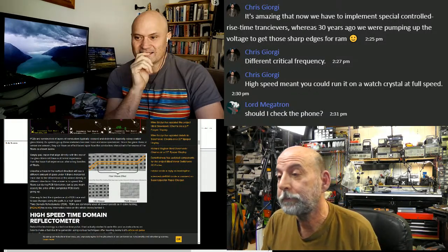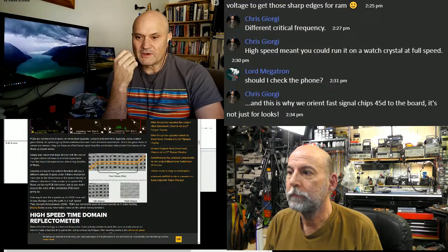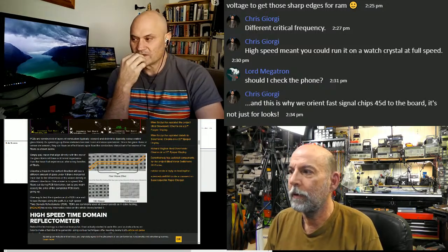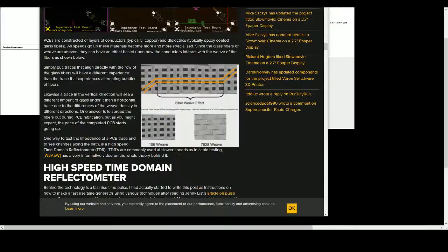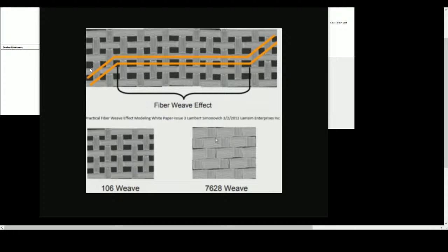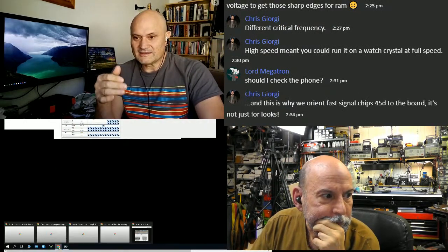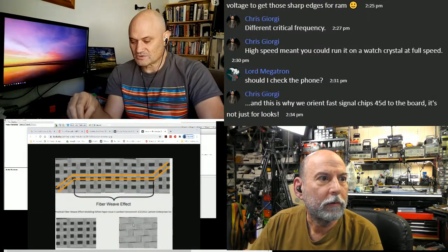Yeah. The theory, though, is common mode noise. Common mode noise is easy to reject because the receiver is only looking at the difference between them. That's why they're called differential pairs. But the problem on PCBs and chips is it's kind of a moot point because the receivers are really two separate MOSFET gate inputs usually, and if noise on a high level, say, is on the trace, it can actually push the voltage up to where it's shorting out the clamp diodes on the input.